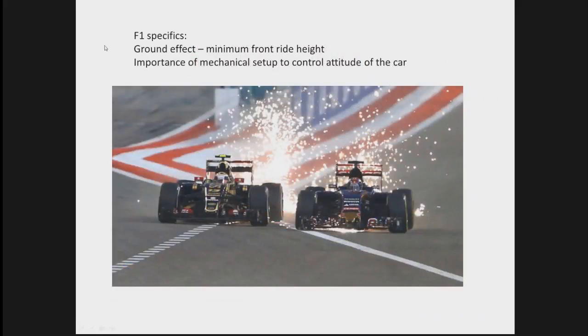The specific of F1 aerodynamics is the ground effect. The cars are so low. The front ride height is not more than 5 millimeter, and actually touching in a straight line, as you can see. So you have to also work on the mechanical setup of the car to make sure you control this attitude and use the ground effect to its maximum.